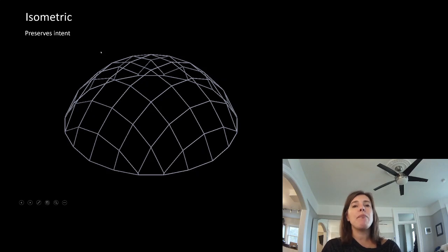This is what I mandate should be on almost any set of drawings that have any sort of complexity visually to them. I find even when I'm working with architectural drawings, a rendering of the building is huge for helping me understand what the 2D representation is trying to convey. If I am doing a project that has any sort of 3D model built into it, I will put it on the cover sheet, and I will say this is not for structural information or pricing information. It is purely contextual to help your mind process what is happening.